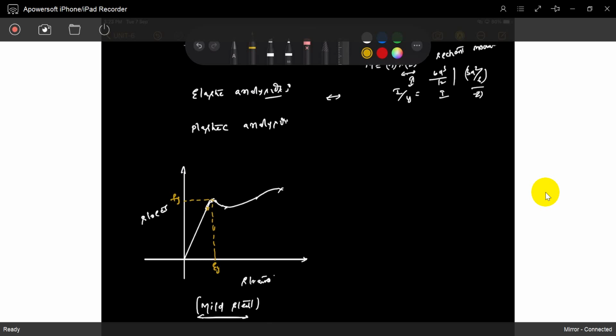I think you did a strength of metals experiment in a steel laboratory, but you didn't because of COVID. If you take a steel bar and get a stress strain diagram of the steel, it goes like this. Where it really fractures, it's a failure at this point. This is the failure point, otherwise the fracture point. The steel bar gets a fracture at this location. But once we cross the yield stress, we take it as a failure.